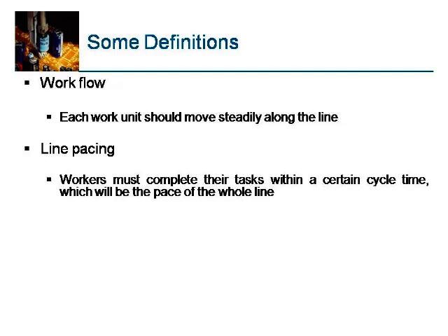When the workers are standing across the line, and the line is moving slowly, the workers are supposed to complete the assembly as per the assembly time only. The pace of the movement of the work part is fixed. Accordingly only the speed is set, and by the time a work part comes to the vicinity of the worker and leaves from the vicinity of the worker, he has to complete the task given to him. Otherwise, you will get incomplete assemblies.